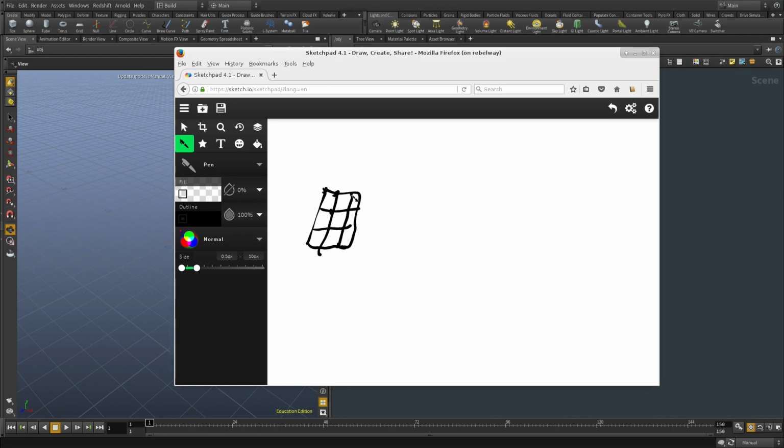And in Houdini we can use a point VOP or a wrangle or anything to change the value of these guys. So what we can do is take these points, and using a point VOP we can take the current position and apply a noise to them and move them to a different position. We can change the point position to be in a different location. We can also change any value alongside P. We can change color, we can add new attributes, we can create anything like that.